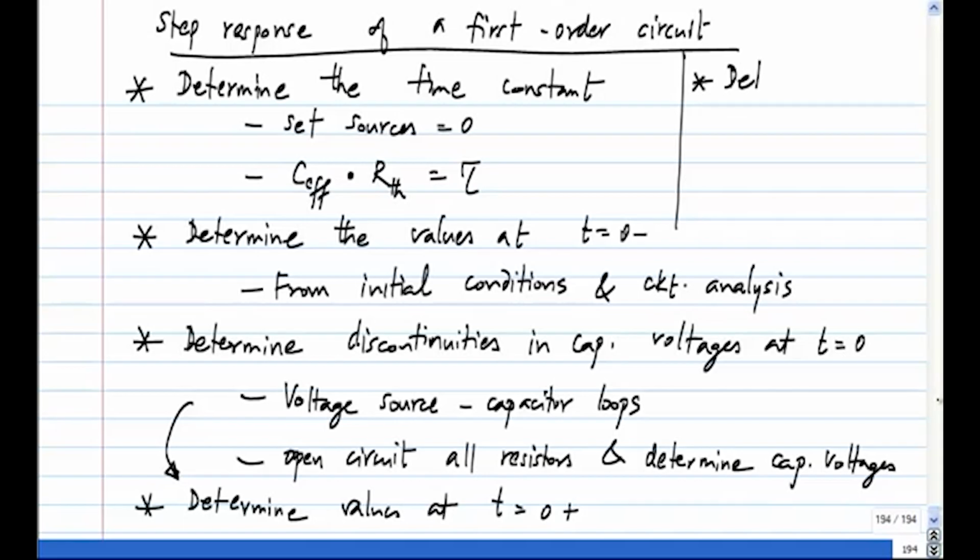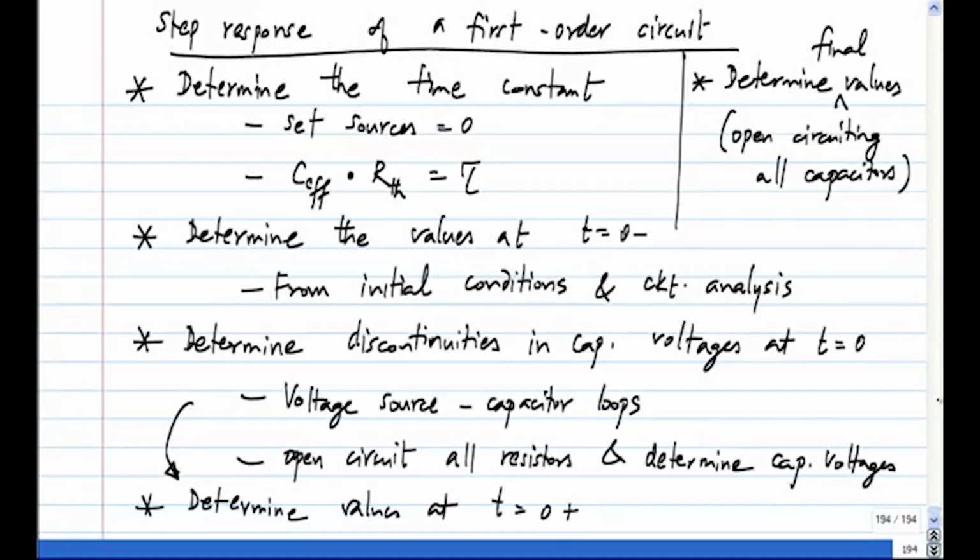They also determine the final value. For this again, you open circuit all capacitors because we are applying piecewise constant inputs.